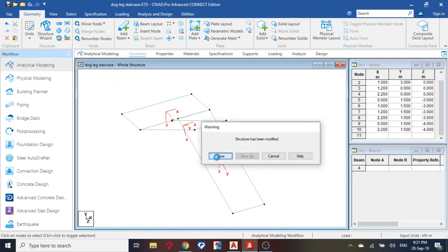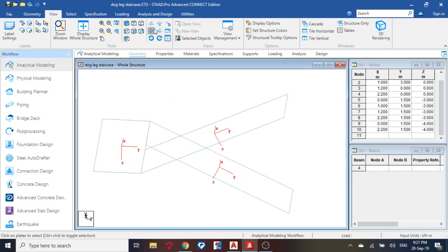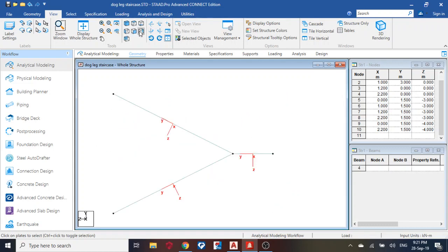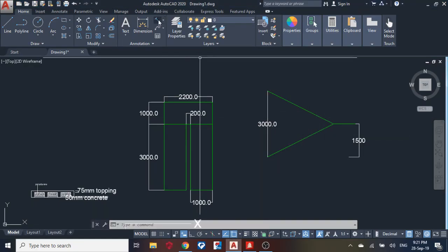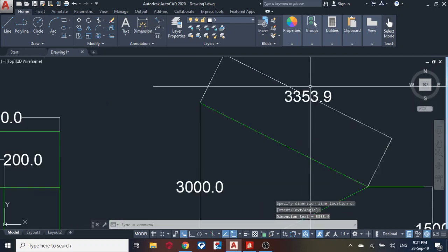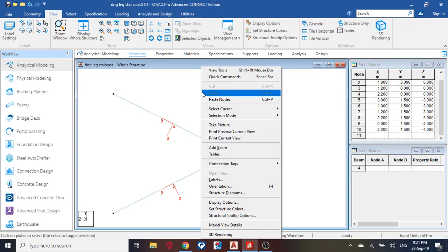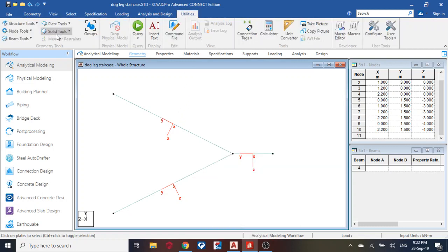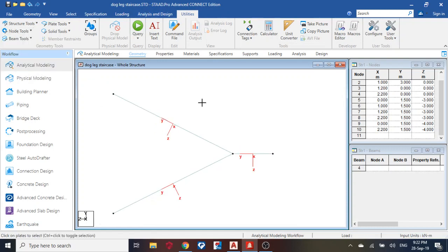Sorry, view, you can rotate it, you can see it from this view, something similar to this. You can see this. So let's get our distance. This is the aligned, so okay, about 3.54. Go to node distance, utilities, node tools, node distance from here to here, so 3.54. Okay, so utilities, node to remove this. Okay, we're on the same page.